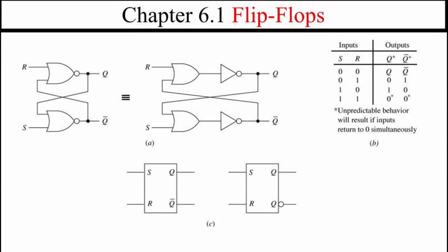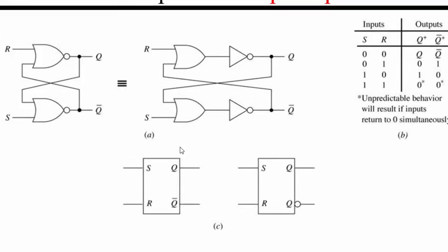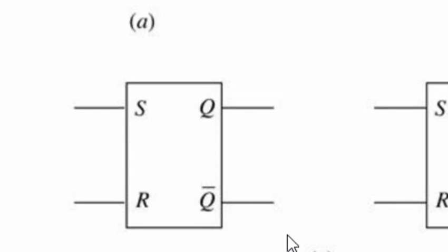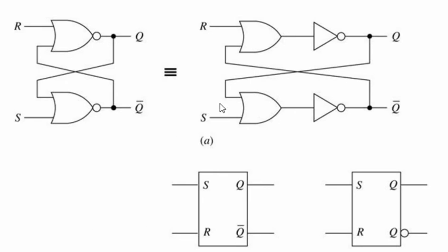Awesome. So our circuit symbol for this is going to be this or this. So you can see the R and the S are flipped positions. This way, when we set, Q becomes a 1. And when we reset, Q bar becomes a 1. And then we can say Q bar, or we can put a little not symbol out here on the end.